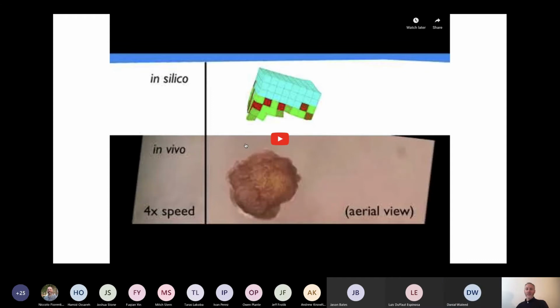Yeah, exactly. So again, this was a successful transferal from simulation to reality, and a lot of the designs do not transfer. This is known as the sim to real problem, and it exists in traditional robots, not just the biobots that you see here. This is an open problem in robotics. How do you guarantee that an AI-derived solution in simulation will transfer to reality? Especially when you're using an evolutionary algorithm. An evolutionary algorithm, like biological evolution, will exploit whatever materials you make available to it, including approximations and errors in your simulation. So this is one big issue about trying to use simulation, is that often it will exploit these inaccuracies that work in the necessarily approximate model of the real world. And because they rely on those details of the simulation, when you transfer them to reality, the plant or the robot does not do what you expect it to do.